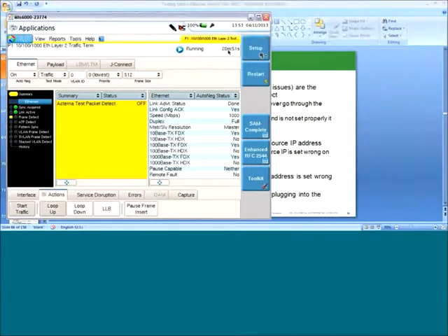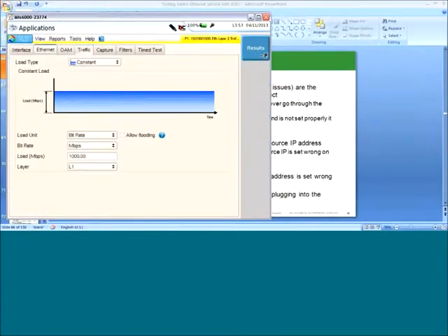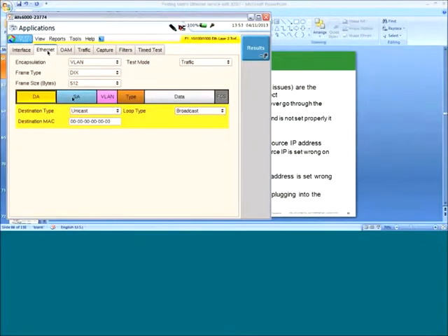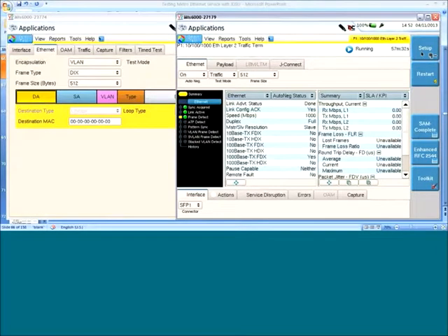Now, what we want to do is load the exact identical configuration on the far end unit as well. In the setup, in the Ethernet here, you'll notice it says destination address 0 and then loop type broadcast. But you can also decide, I don't want to use the broadcast option, I want to put a particular MAC address. So you just put unicast here.